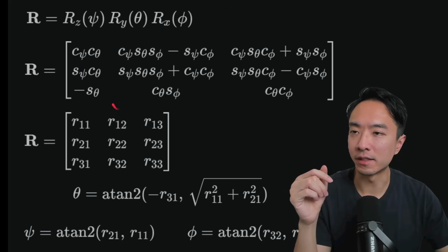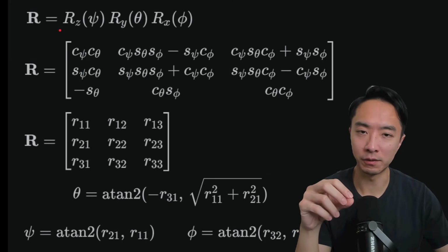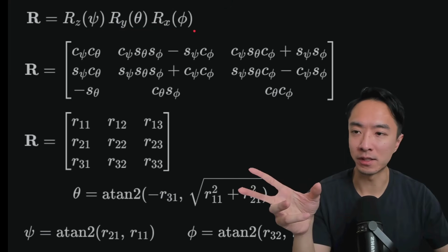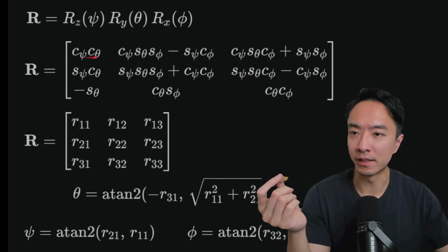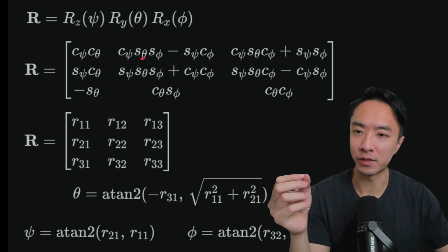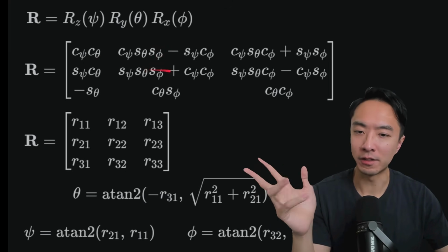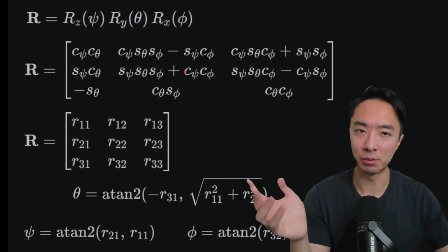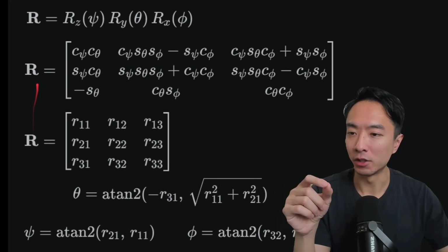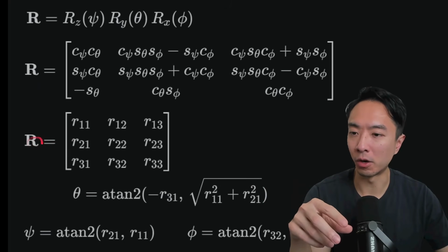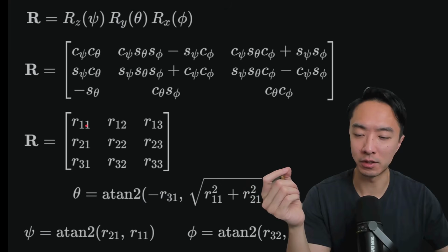So here, this is the rotation. When we have the 3 rotation matrices multiplied out, you could expand all of this. The C is for cosine and S is for sine, and we have the subscripts for the different angles. When you have this all expanded out after you multiply it in symbolic form, you compare it with the general form R using just the 9 components of your rotation matrix.